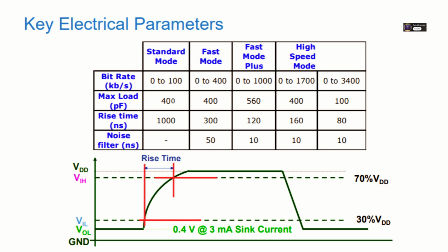Which explains why I²C is usually for short distances, right? Inside a box, not across a room. Precisely. Keep it short. Typically within a single PCB or enclosure. Meters of cable will almost certainly cause capacitance problems unless you take special measures like lowering speed drastically or using bus extenders. Makes perfect sense.